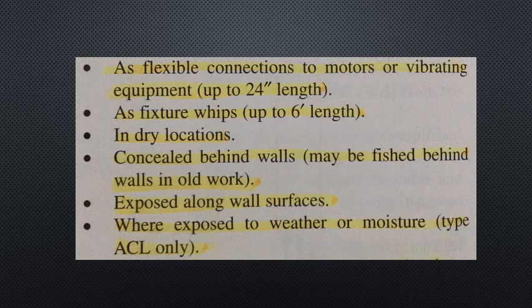Armored cable must be properly supported at intervals of 4 feet 6 inches, and within 12 inches of terminal boxes or fittings. When routing BX cable through wall, floor, or ceiling members, the member must be drilled through the center or notched and covered with a metal plate to protect the cable from nails.